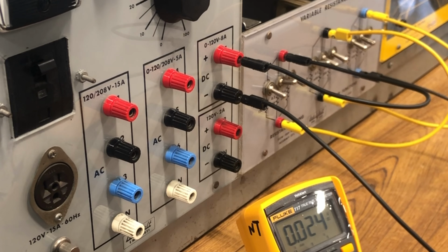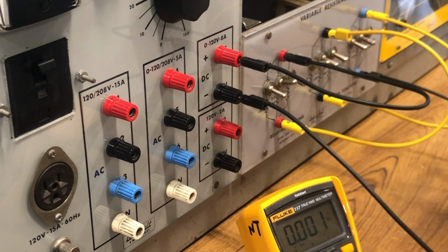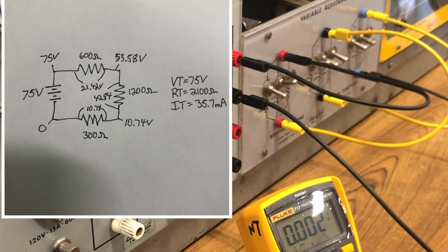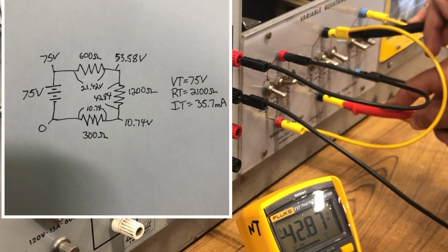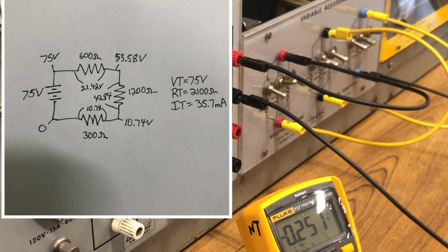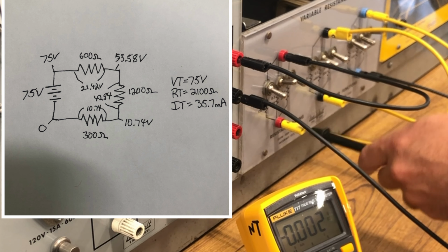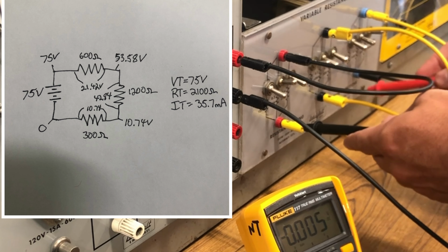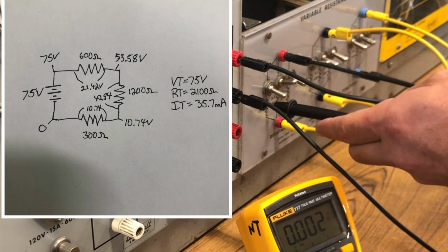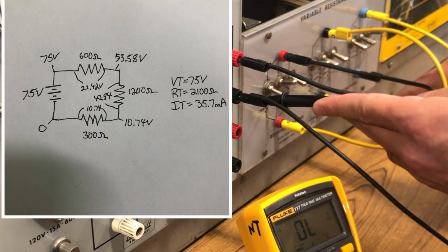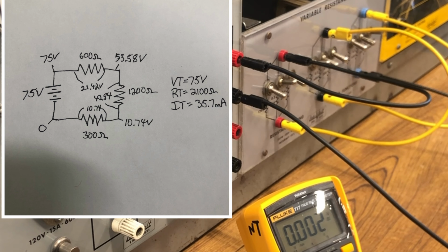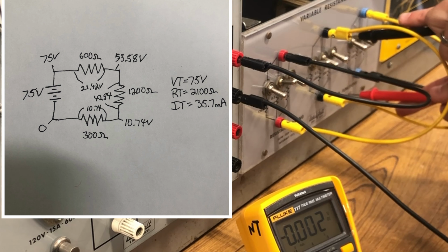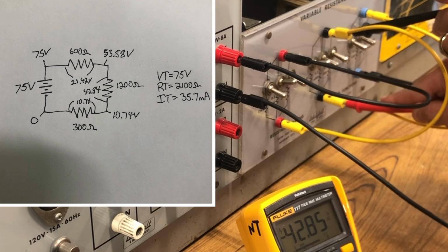All right. Now what's the voltage drop of R2? 42.84. So if we go across it, remember how I was telling you it reads the difference of potential? 42.84. Look at that. Now, think back, what was this reading right here? 53.58. Okay. What's the reading right here supposed to be? 10.74. Okay, so 0 to here, it's reading 11. So 11 minus 53 is supposed to be the voltage drop across this, right? Yeah, 42. Okay.